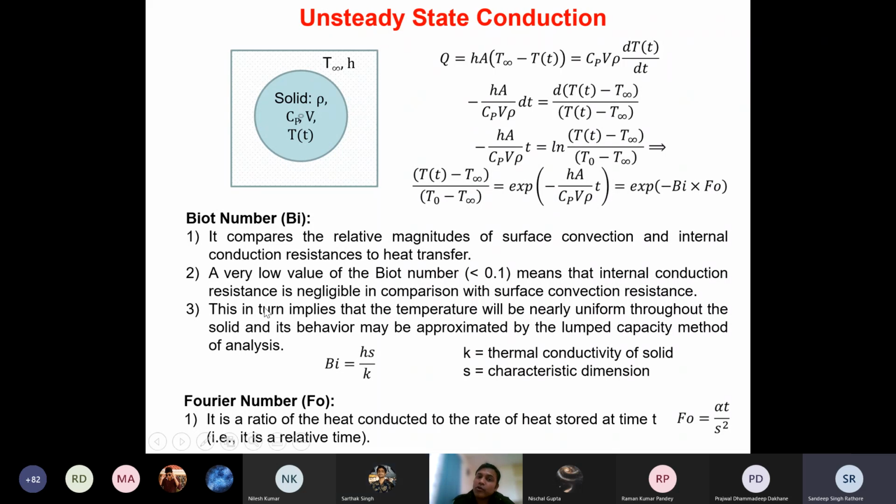Okay. So that is why you are using T infinity minus T, isn't it? This accounts for both input and output. This is the net heat input to the body, isn't it? This word net is very important here. So this T infinity minus T(t), this delta T into hA, is the net heat input by convection to this solid.